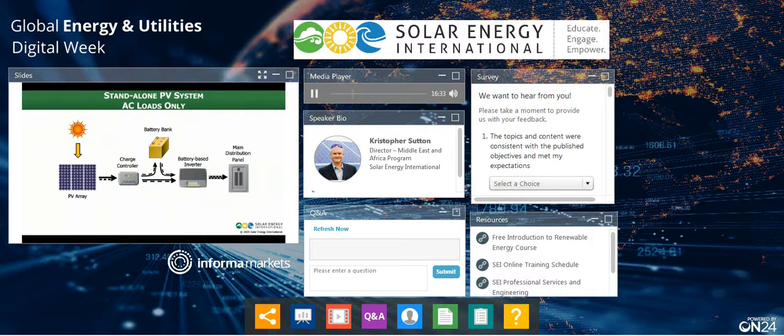And then at that point on the right, we are at an AC output now. So now we have an AC output for that system, and we run that into an AC distribution panel or MDB, whatever our load is and our distribution from there. So the PV array does the generation, the charge controller regulates the PV, the battery bank is our storage, and now we've added conversion of DC to AC and consumption in our main distribution. So that's our standalone AC-only type of system.